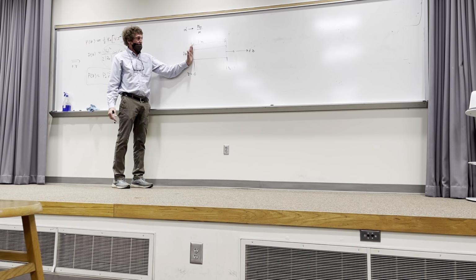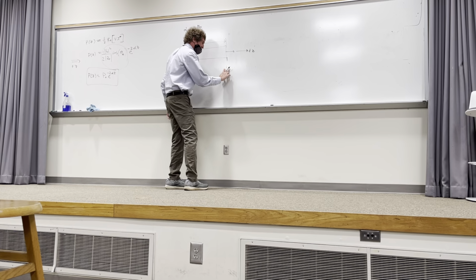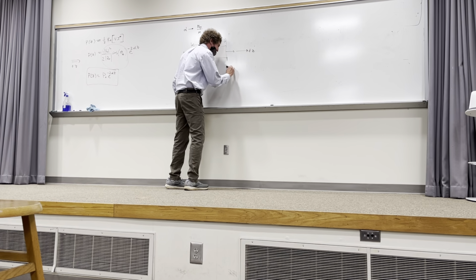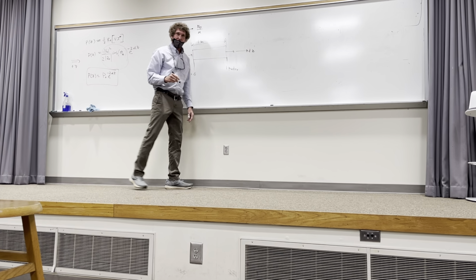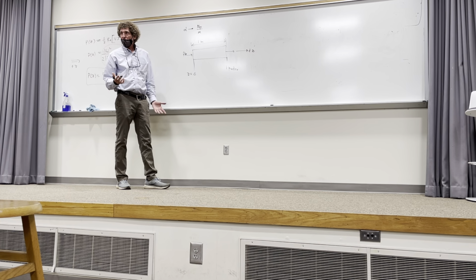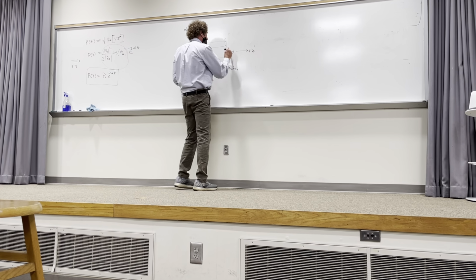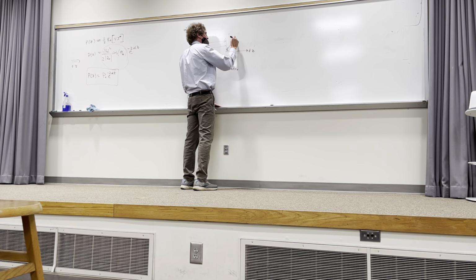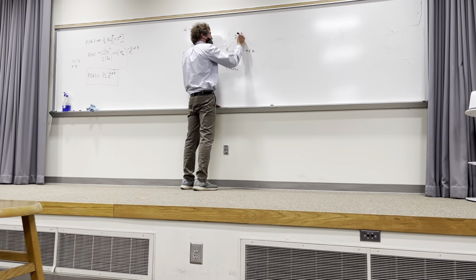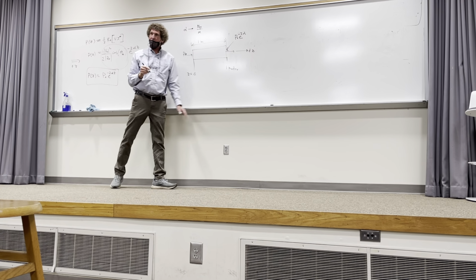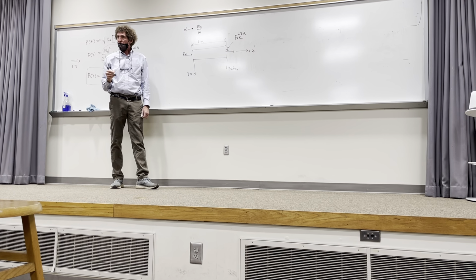This is a meter. Not a very good meter, but it was meant to be a 1 meter chunk. I have P0 here. That means right here at this point, since it's attenuating, the power coming out would be P0 e to the minus 2 alpha. You all follow me? Does that make sense to everybody?